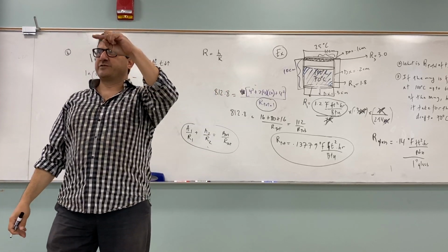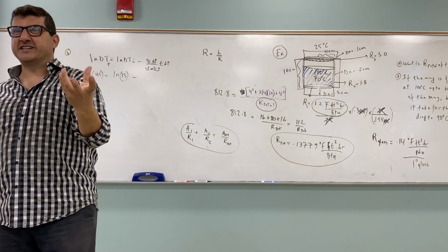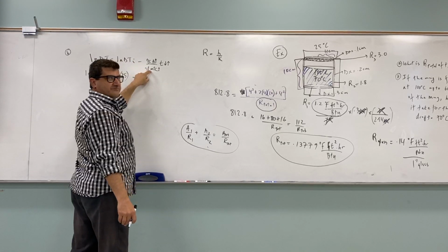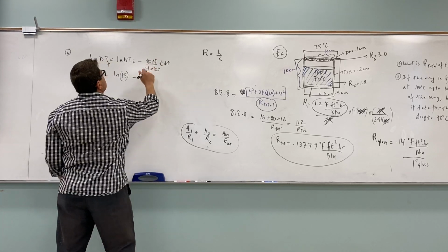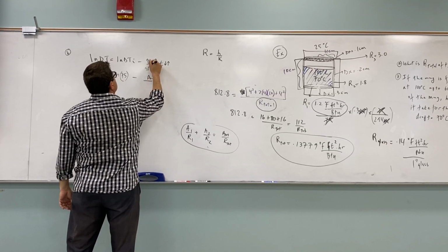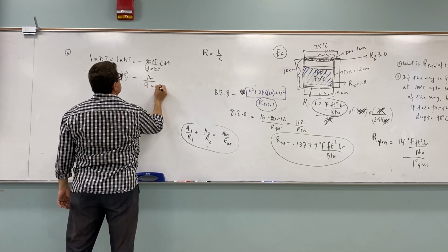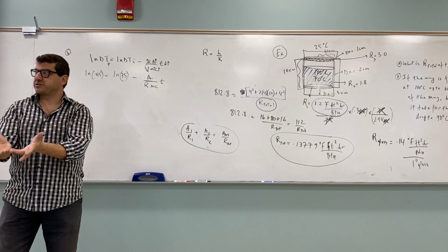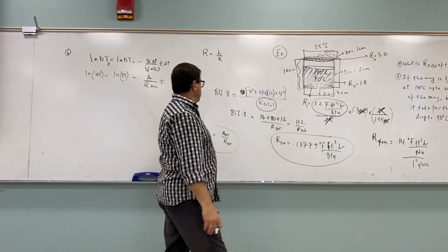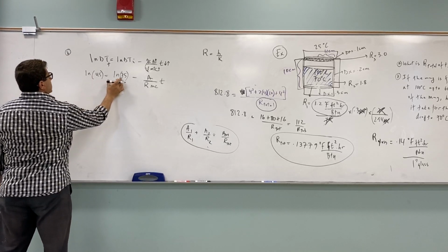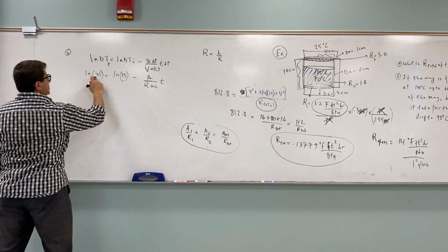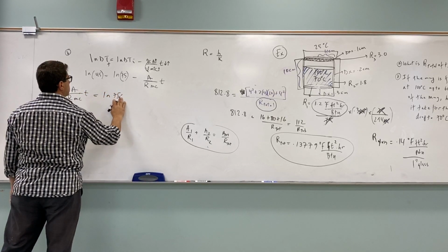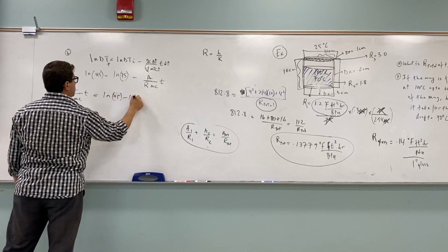So basically the K over D is the reciprocal of the R factor, the net R factor of the mug. You can see the K over D. So we can replace K over D by R in the bottom. And that's the net R factor of the thing. So we can just say A over K can come down to the bottom and make this R M C. Okay, so we could bring this to the other side. So we have A over RMC, T, ln of 75 over 45.